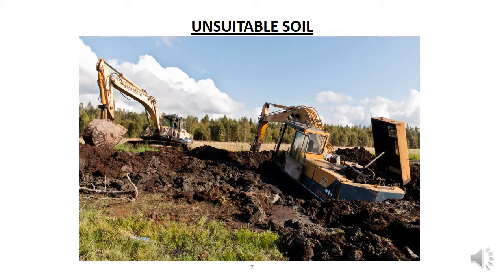There may be soft or unsuitable soil that needs to be removed or replaced or strengthened to enable them to support roads. This photo shows soil that is too soft, so soft that it cannot support the excavator. Most soils are strengthened by compaction to allow a more compact and stronger formation. Softer soils or roads with higher loadings may require stabilization using lime or cement. We will look at these processes in a later video.